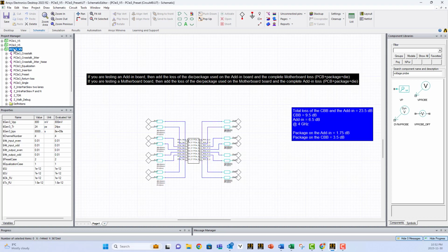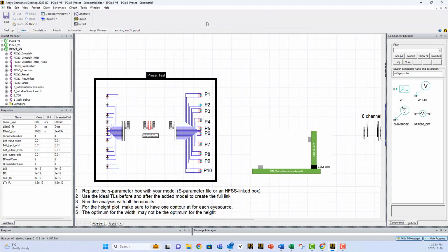We go back to the global variables and they are here. Attenuation input even, attenuation input odd, and attenuation output even, and attenuation output odd. So you have to enter these numbers for the input and for the output, depends on what you are doing. You can set them to any value you want. You can set them to the values specified in this table. You see this table provides you all the information about the values as per the specification for that standard. And you will find similar thing, as I said, for all the other circuits and all other standards. Or you can keep them 0. Maybe you just want to test your bare PCB alone. Now we click pop-up to go back to our circuit.